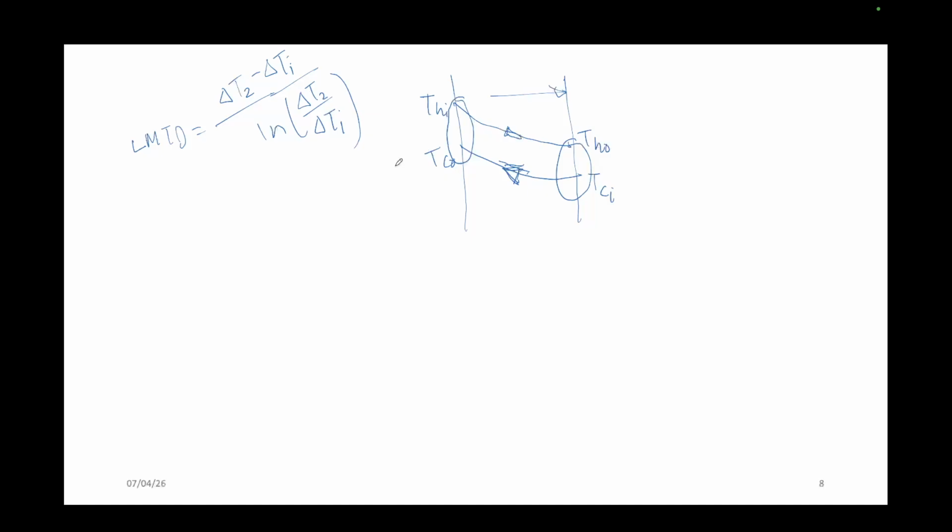So why is the LMTD method necessary? Basically, in the LMTD method, you have Q equal to U A LMTD, right? So basically this A is not known to us. Generally, you know Q, you have U, you can find out the LMTD from all these temperature values. Then the area you can find out. This area is the design parameter. It is a design area, not the actual area.